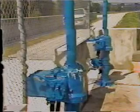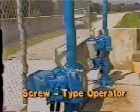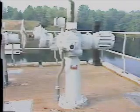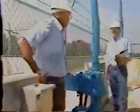Instead of a hydraulic operator, you may find a screw-type device run by an electric motor. The rotation of a threaded shaft, which is attached to the gate stem, raises and lowers the gate leaf. When inspecting this type of operator, check for sufficient lubrication and for structural damage, such as bending of the shaft.